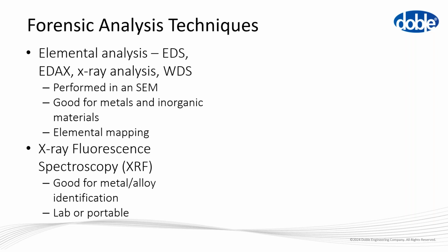We also have an X-ray technique called XRF, again, good for metallic materials. It can be portable. There are portable units, which look a bit like a large handgun, that you can take to site. It's also very good for particles in oil, if you don't want to have to try and filter them out of the oil.